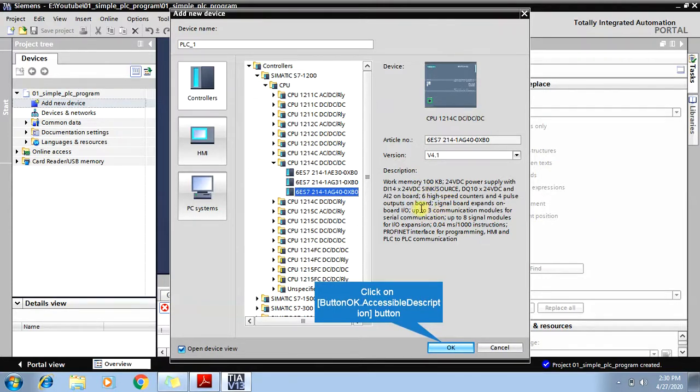Okay, then this also has two analog inputs on board. Basically this S7-1200 1214 DC PLC has analog inputs which only support voltage on board. So if you want a current analog input, then you need to add a module here. An analog input/output module has to be connected here, or else you can create it using a signal board. Okay, it is present here.